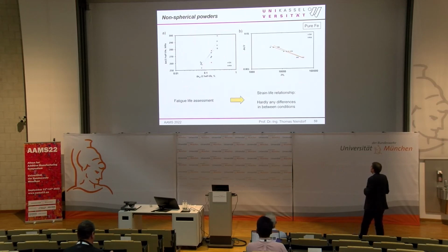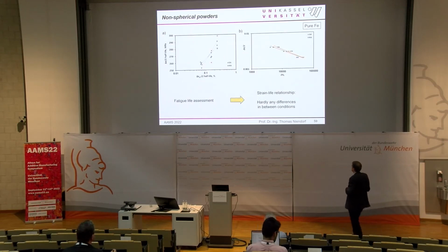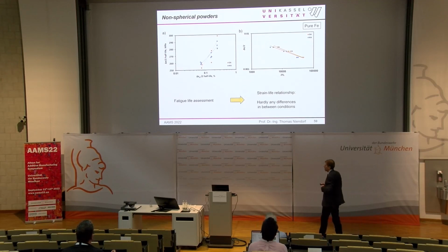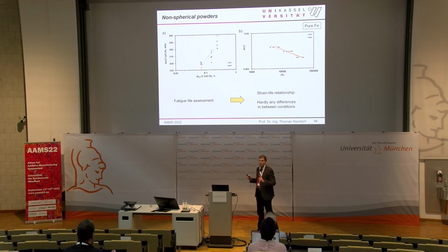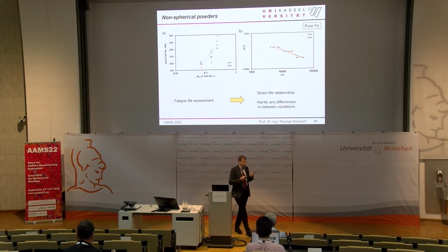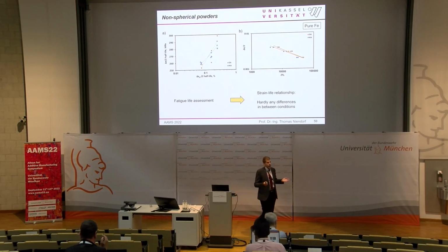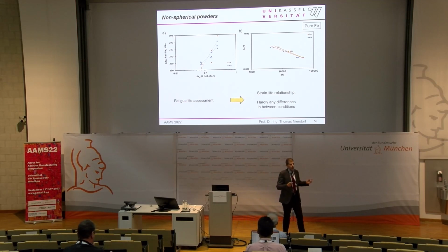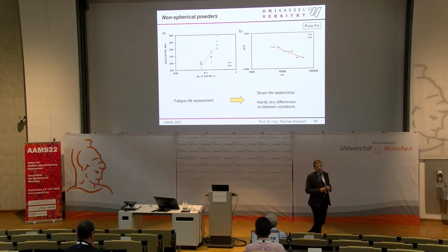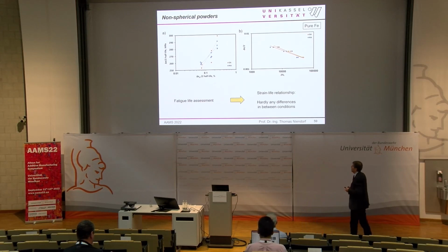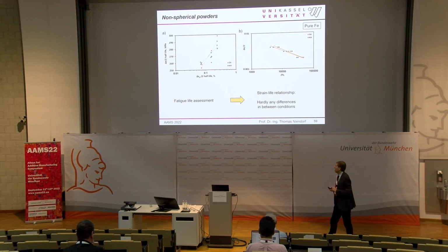Looking at Wöhler type curves now plotted versus the strain value at that point, again, a reasonable fit of both conditions. So from these data, we just derived the conclusion that water atomized powder can be used even if this will be used afterwards in an environment where cyclic loading plays a role.